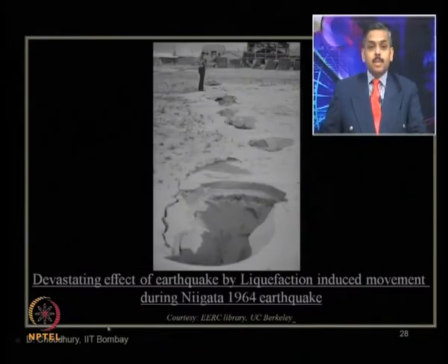This is another picture which shows the devastating effect of earthquake by liquefaction induced movement. So, after the liquefaction, the soil, or watery soil I should mention, has moved out from this location and created these big voids. So, this liquefaction induced movement has occurred at this site after the Niigata earthquake in 1964 in Japan.